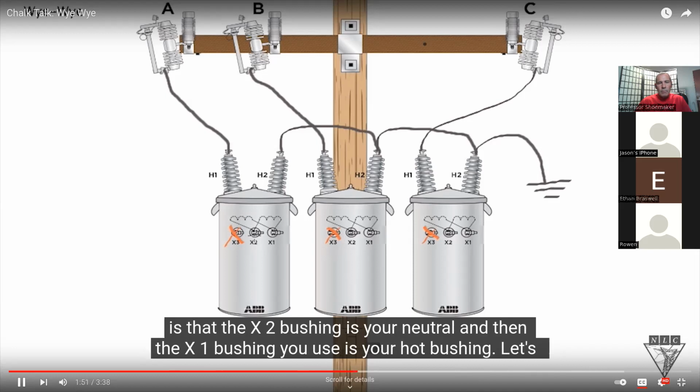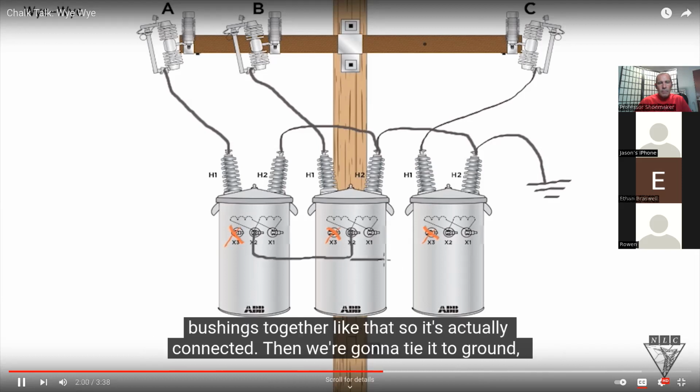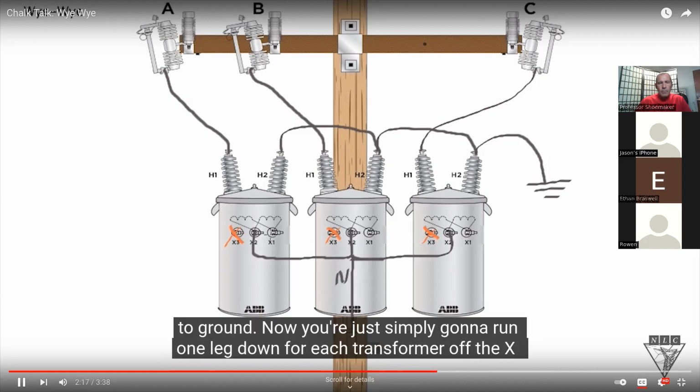So let's do the secondary connection now. The first thing we want to do is tie our X2 bushings together, and then tie it to ground. That's our neutral on the secondary side. X2 bushings are all tied together and then tied to ground.